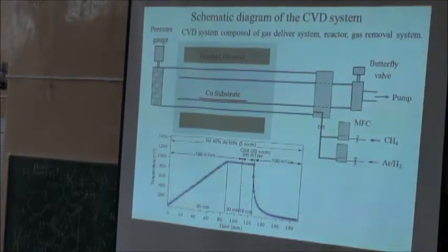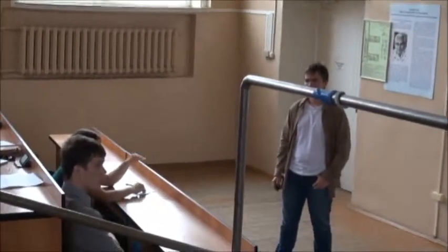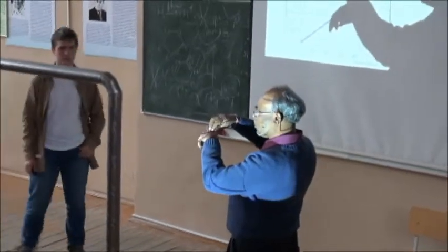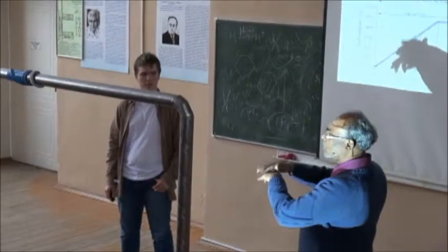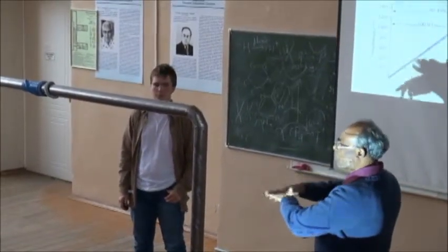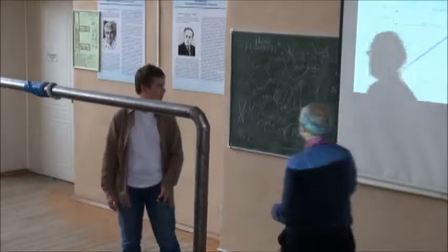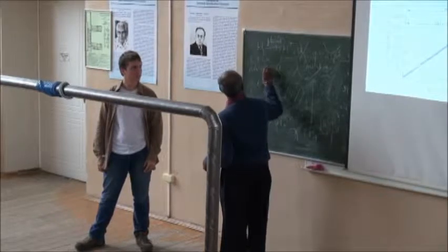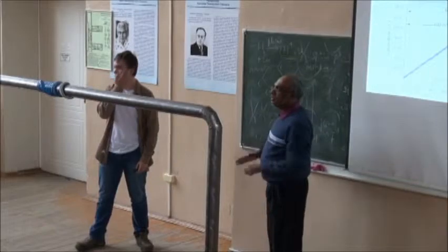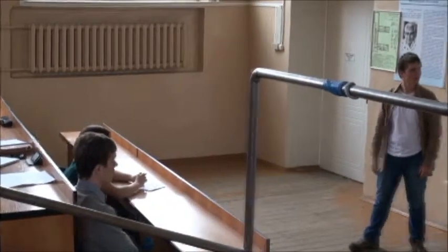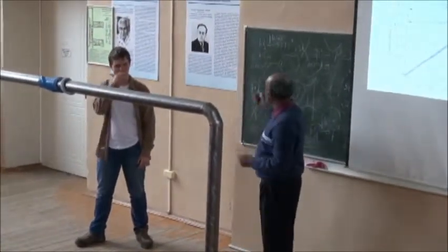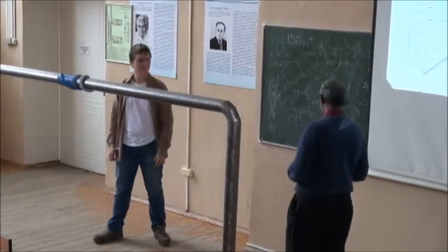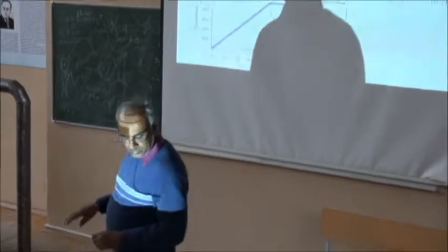I have a question. Do you have a diffusion of ammonia borate inside the copper? Yeah, it's the same thing. What happens is it's a vapor, right? So boron and nitrogen vapor comes, and then it spreads on the copper because there's no miscibility. Same thing happens with the carbon. Carbon and copper, or boron nitride and copper, they don't mix, even at high temperature. But if you use iron or nickel, that's why you grow carbon nanotubes, because they mix in. So with copper, there's no miscibility. It's only just spreading over.